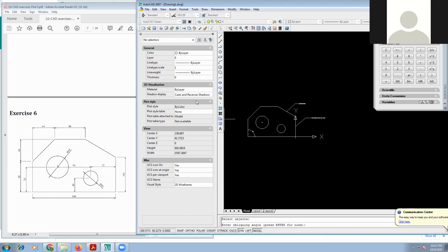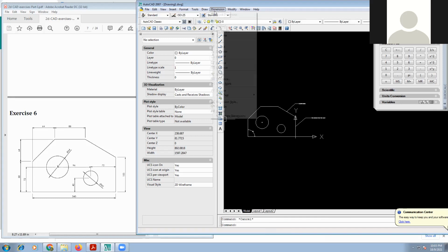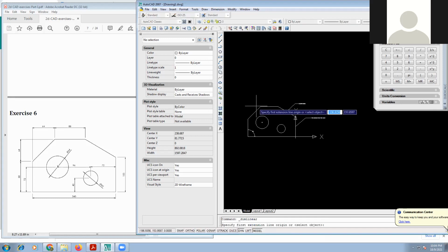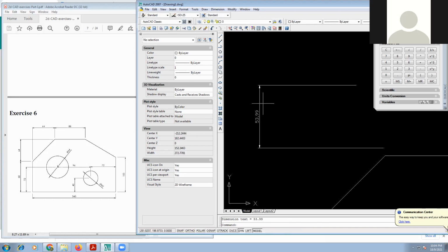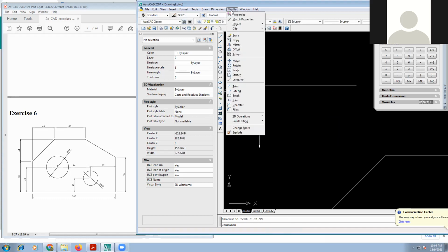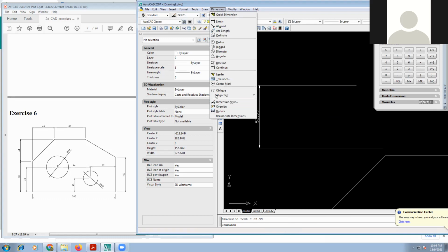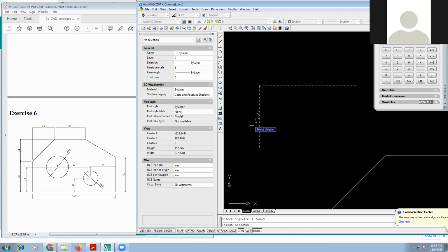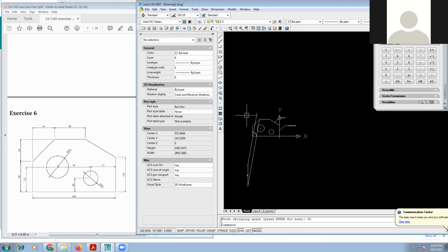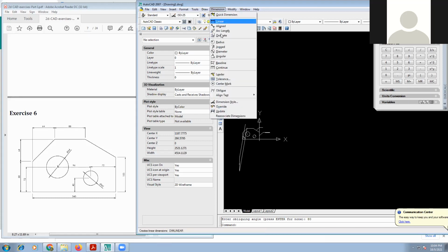For example, I'm making a linear dimension here. Then I put oblique dimension, select, enter, maybe 80 degrees. This 80 is too much. If you want an angle like this, you can just change it. This one is also not important, don't worry about it too much.